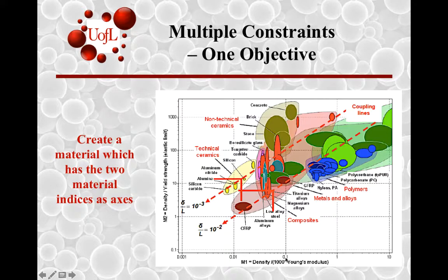Because of the difference in numbers, we modify the x-axis a little bit. And so you end up having this plot, and you'll see that the top of the plot is dominated by ceramics, the bottom corner is dominated by metals, some carbon fiber reinforced plastics, or some composites, and the polymers are right here on the top right hand corner.